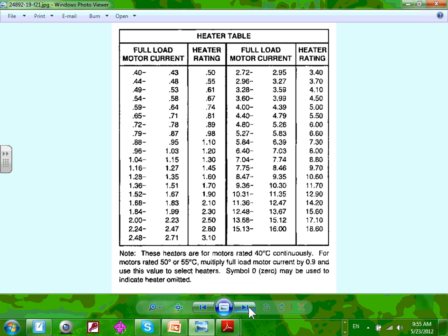Okay, now you're not electricians, but if you guys are project managers on a project, if you have the overload, you guys remember the overload that we did? When you do overloads in an explosion-proof location, guess what you need to do? You need to go readjust the overload based on this table, if in a Class 1 Div 1 location. Because if you put the overload too high, the amount of energy coming out of an overload condition could ignite the surroundings and could exceed the rating of the explosion-proof equipment.